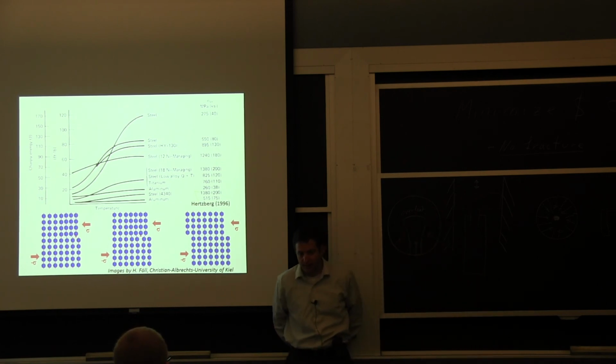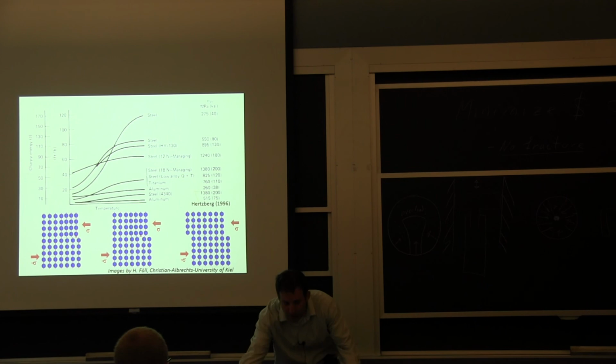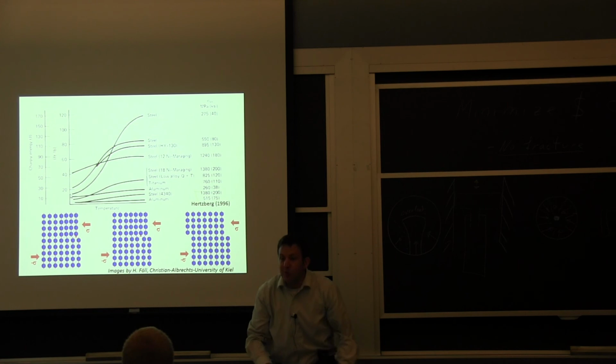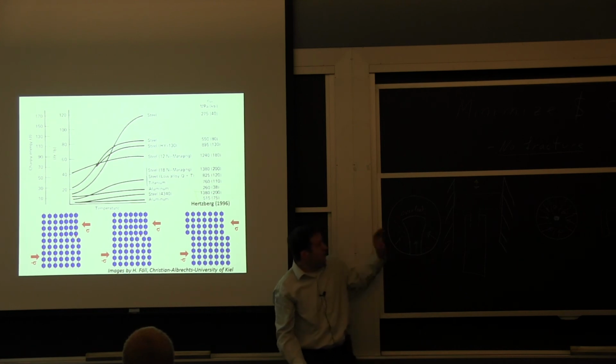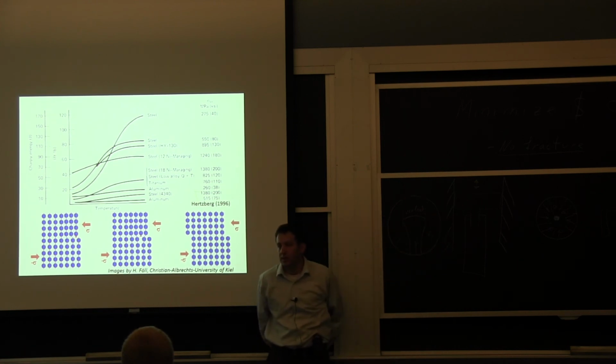And that is where also you taper off. So if I look at the steel curve, this is kind of a regular structural steel. It's very high, it goes down, and then eventually it's going to become less temperature dependent again because we're only dealing with the brittle behavior side of the equation. That's why we have this inflection point there.